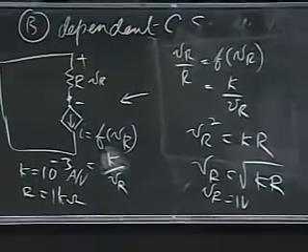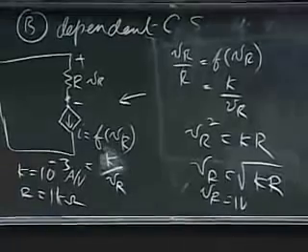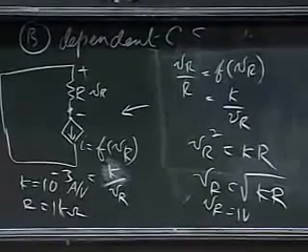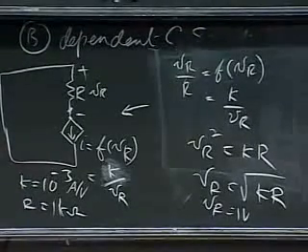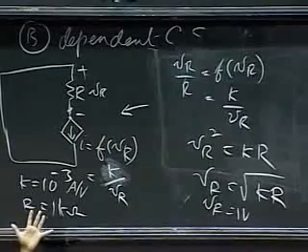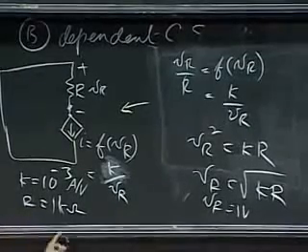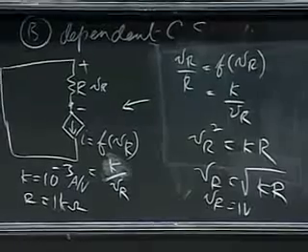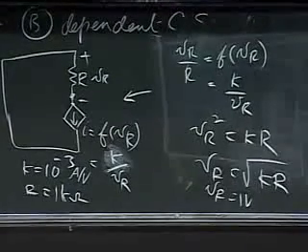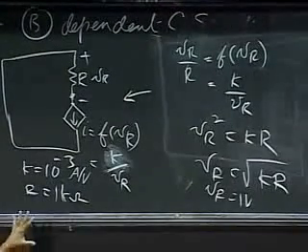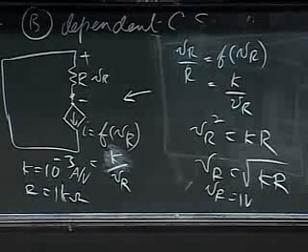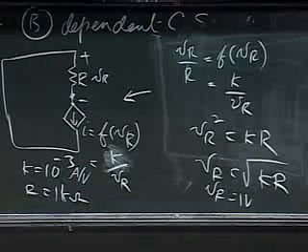So again, as long as you remember that the dependent source is simply another little circuit element, and you usually draw just the output port for dependent sources and reflect the way that the control affects the current, that will suffice, and you get, through the application of the node method, the variable you're interested in.